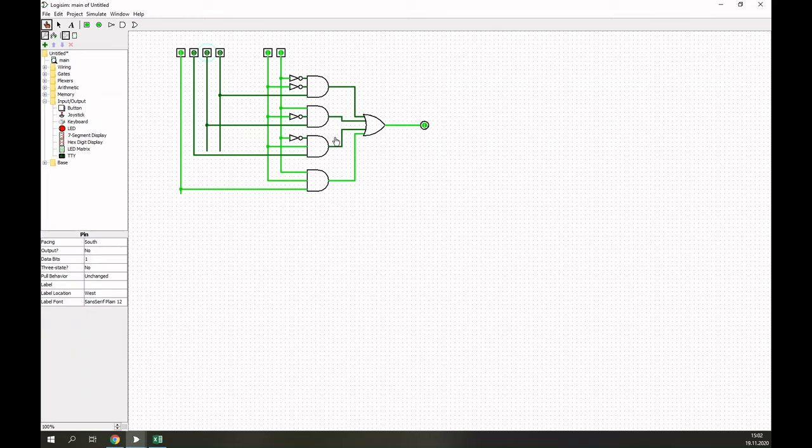So, and therefore I can do addressing, or I can do a multiplexing, so that I send over one single line according to this setup. So for example, if I have a clock pulse, I can switch between the 4 different bits, and if the receiver receives it in the same way, it can also select the right position and rearranges it with a demultiplexer, for example. So therefore I can have a mechanism to sequentialize bits, or I can have a mechanism to address bits. This is quite important for calculation machines. Let's go to question number 6.